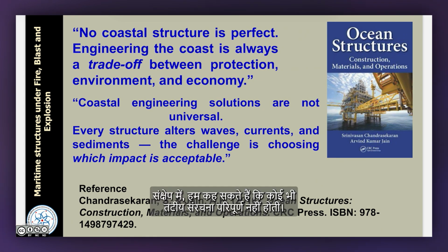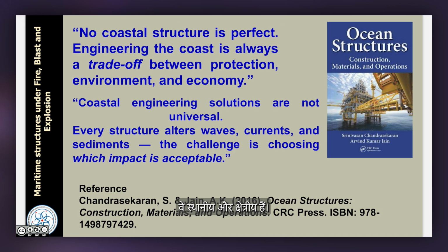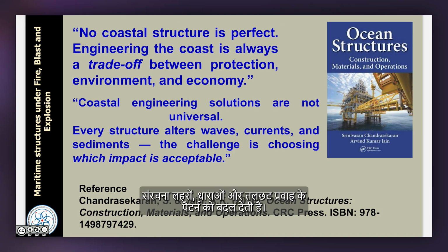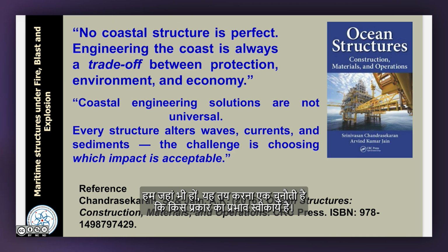Friends, as a summary, we say that no coastal structure is perfect. Engineering a coast is always a trade-off between protection, environment and economy. Coastal engineering solutions are not universal, they are local and regional. Every structure built along the coastline for coast protection alters the waves, current and sediment flow patterns. The challenge is choosing which impact is acceptable.